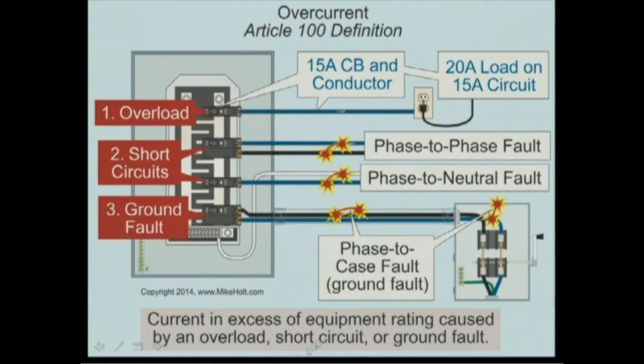It also includes short circuits. That means it's a phase-to-phase fault, or phase-to-neutral fault is a short circuit. And a ground fault is going to be phase to enclosure where that fault current is going to return back to the source. So this is real important.